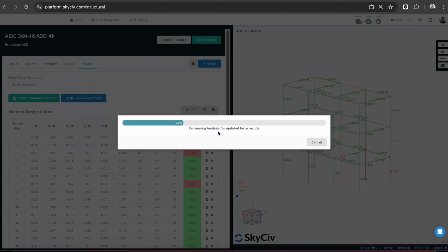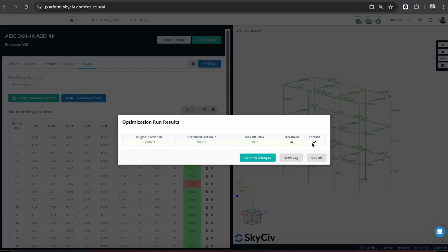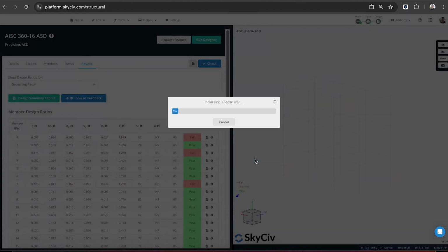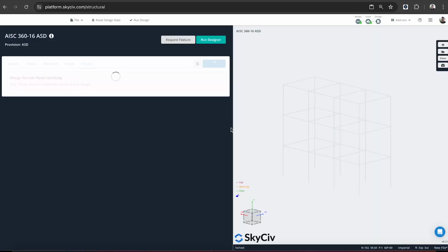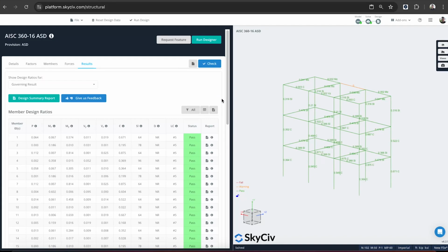I can see now that it is rerunning the analysis in between, every third section that it's testing. So it should have a more up-to-date analysis for each of the sections. So you can see it does take a little bit longer, but it should produce a more accurate result. And to get it to work each time, you would set it to 1. 1 is the best, because we'll always rerun the analysis in between every cross section. But just for the sake of this demonstration, I think it's saving some time, just using a higher analysis interval. And you can see the difference that made now.